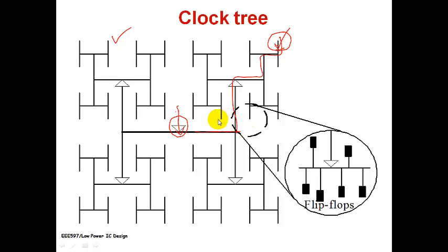Whereas if I go for taking this particular thing, I have here division, and for this particular thing I have this. What I have in this arrangement is that each and every path I take for the clock, I ultimately realize equal time at which the particular flip-flop is supplied by the clock. I would want the clock signal to travel through equal paths whatever the clock elements are. We try to manage and we get the H clock tree in this manner.